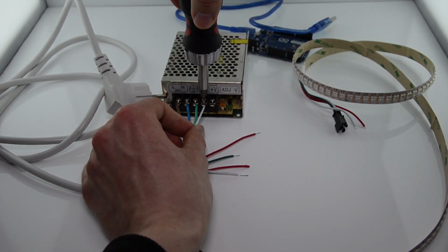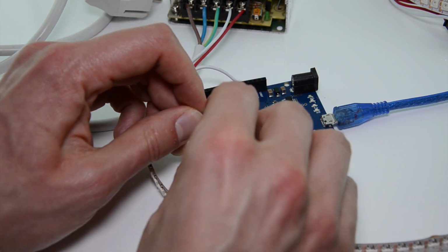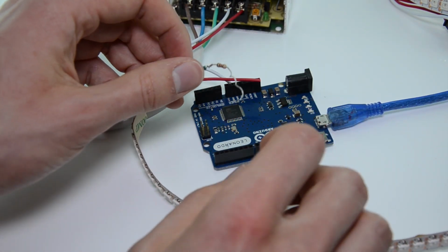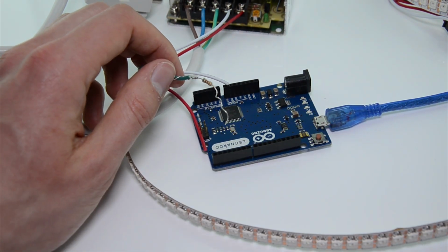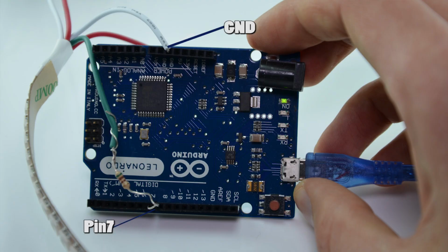Now I connect the white wire of the LED strip to the negative pole and the red wire to the positive pole of the power supply. Now I take a 470 ohm resistor and connect it to the green data wire of the LED strip. One white wire of the LED strip is connected to GND of the Arduino, and the green data wire with the resistor is connected to pin 7 of the Arduino.